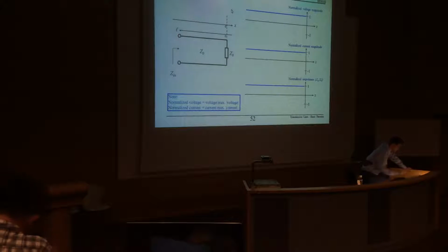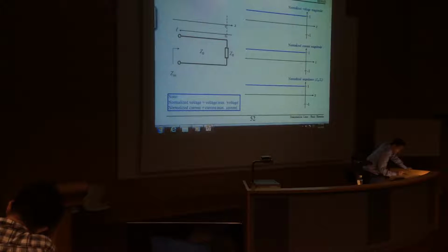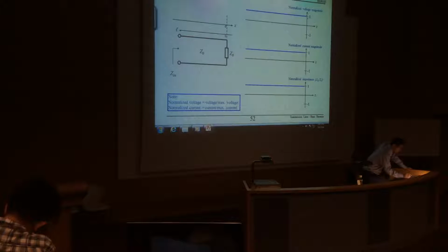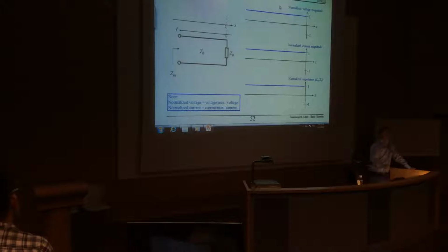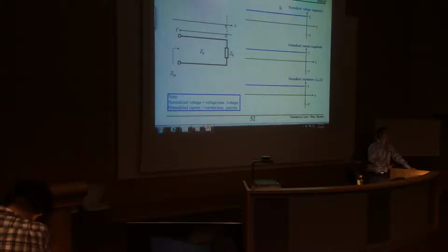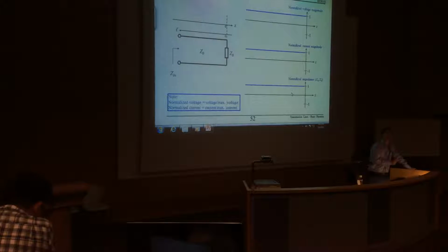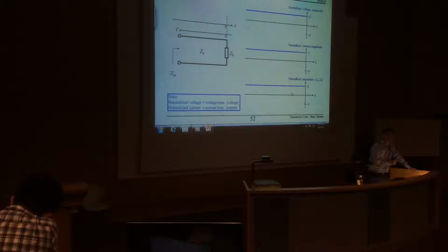For this case, as we have already mentioned, it is a traveling wave with no reflection, so the magnitudes of the voltage and the current are constant. This also means the SWR should be equal to 1, right? Previously, when we mentioned SWR, it was the ratio of the maximum to the minimum. Now it's constant, definitely, so for the voltage or current, the ratio is 1.